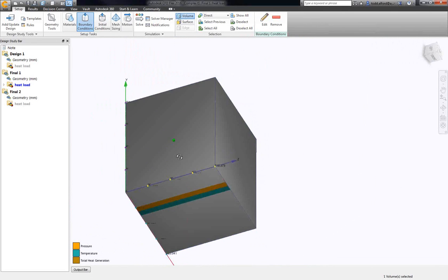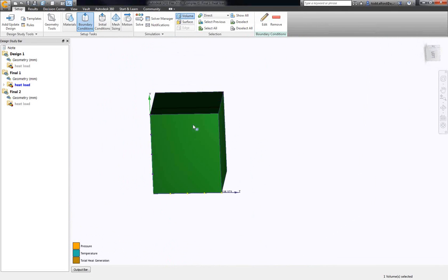Not completely 100% realistic. I probably should have done it more of a bucket, but I thought I could save myself some mesh and get some initial results and have something fairly decent to show you guys, and could always tweak those other settings. If I really wanted to dive into it, that's where I would be playing with the simpler model to verify that my air domain is going to work before I kick in the full geometry, because this guy takes about a day to run.